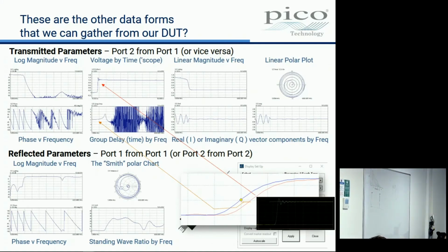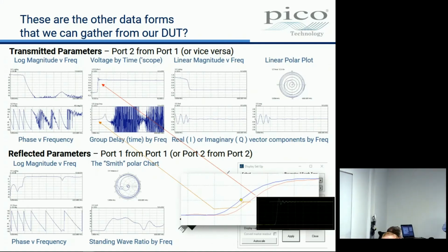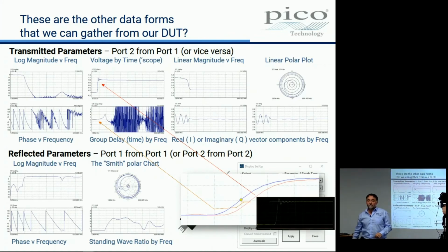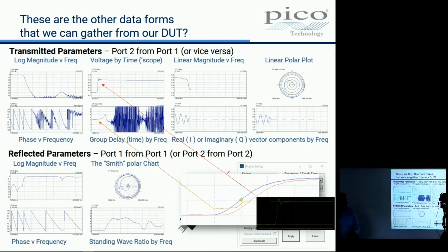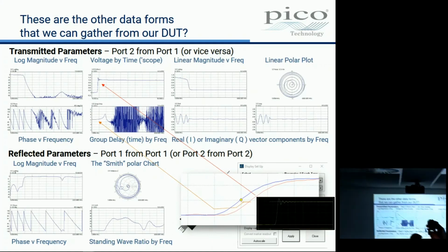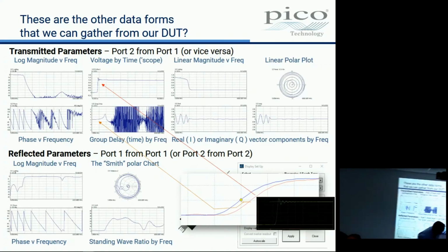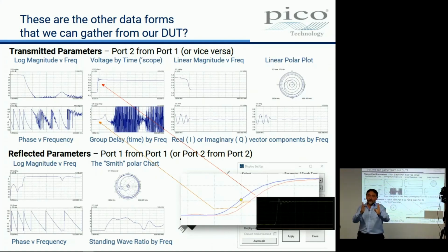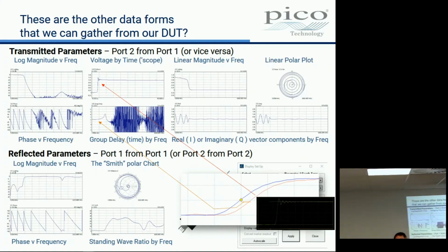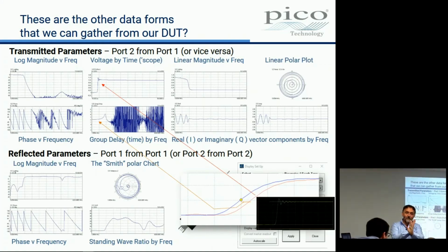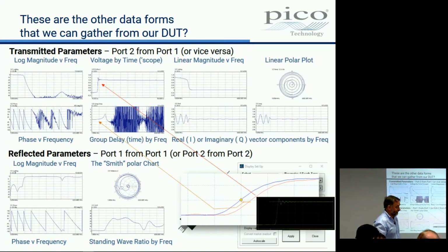Seen that before? Group delay. And we saw it, didn't we? We saw it on our pulse when we looked at, here it is, look. The pulse shape has been corrupted. You'll have to remember it's not very visible here, but we had this ringing, and this is due to the way the filter rolls off and the fact that group delay is sliding all the harmonics with respect to one another.